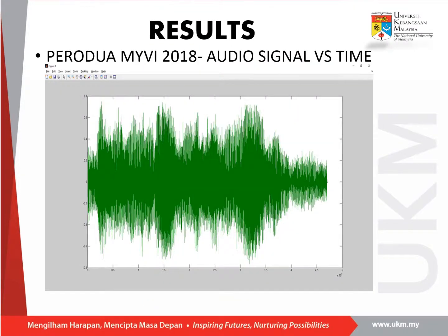Okay, after we record all the sounds from the cars, we need to save them and then import them into MATLAB. By doing that, we can analyze more about the signals. After we import the file into MATLAB, we need to write some code. Later, I'm going to show you the code, and this is the graph showing audio signal versus time.